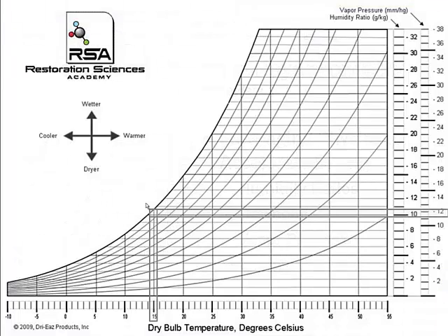When we look at a psychrometric chart, which is the typical instrument that we'll use to understand psychrometric principles in a drying environment, we can calculate for any one of these principles. And what we're looking at on screen right now is a measured temperature of 15 degrees Celsius at a saturation, meaning 100% humidity or completely wet, full of moisture. Where these points intersect on the chart at 15 degrees and saturation, we can see over here on the right-hand side of the chart a couple of different calculations, and one of these being the vapor pressure associated with the water vapor in that sample.